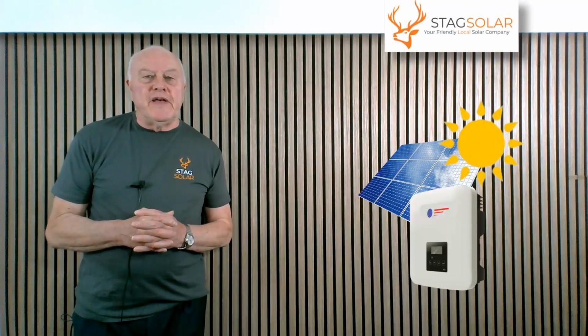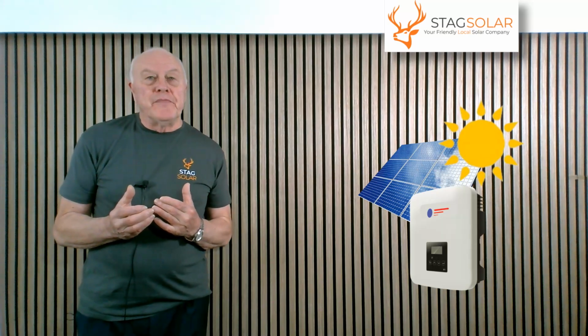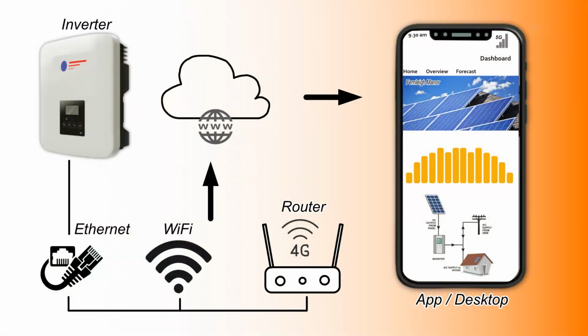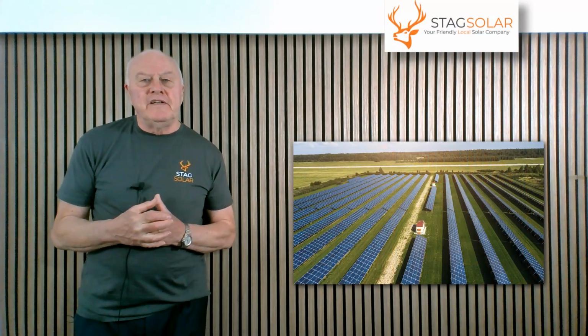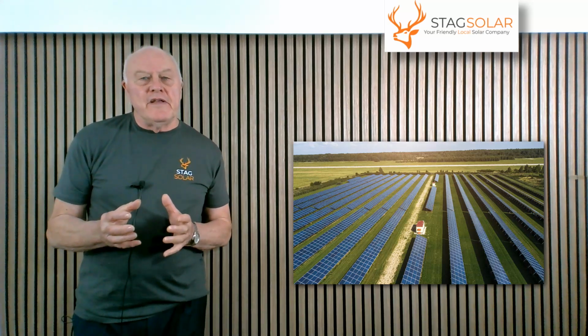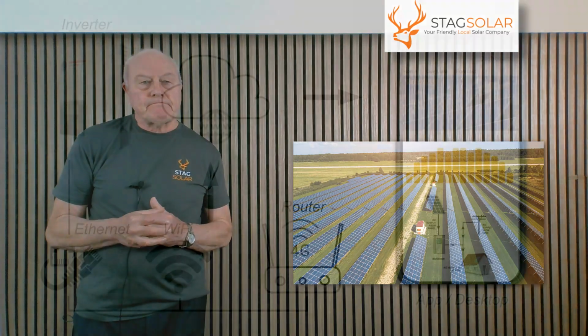So the inverter in effect needs to be able to talk to us and let us know straight away if there's a problem. So how is this achieved? Well, the answer of course is that the inverter connects with the internet via an Ethernet connection, Wi-Fi, or in the case of a location where these options are not available, a 4G router or similar device can be used. An example of this might be in an agricultural setting, for example, where the installation is in the middle of a field.